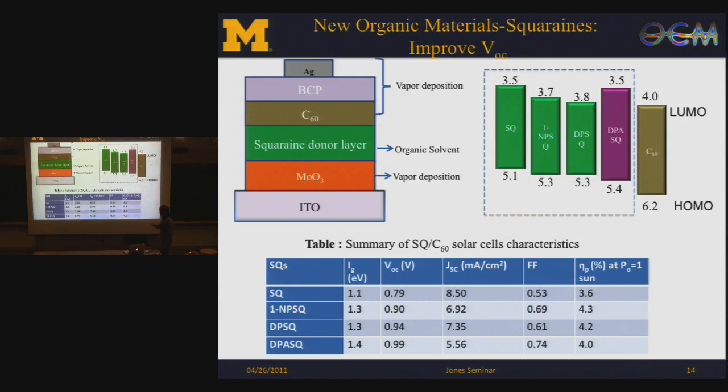At the same time, these two are good materials. The fill factor is around 0.74. So we will take advantage of these two new materials. We want these two materials to contribute to photocurrent, but at the same time, we don't want to lose the VOC and the fill factor. So this gives us a huge chance to improve the photon response throughout the whole wavelength region.